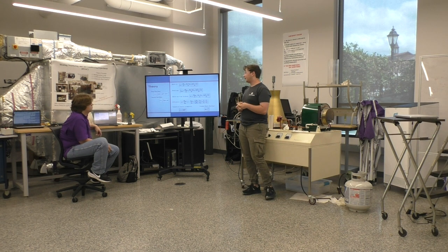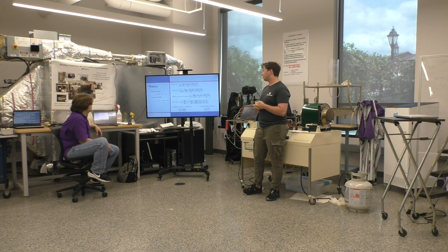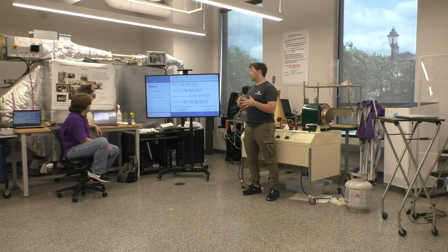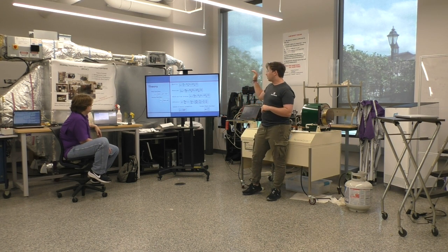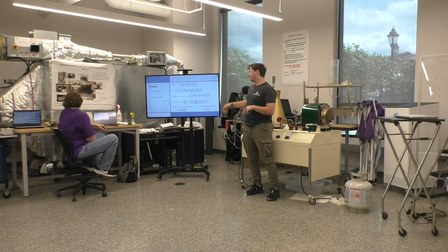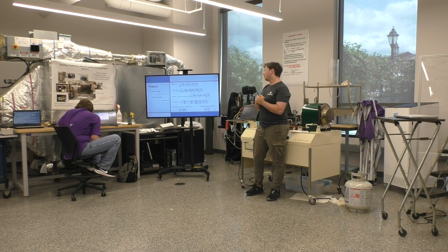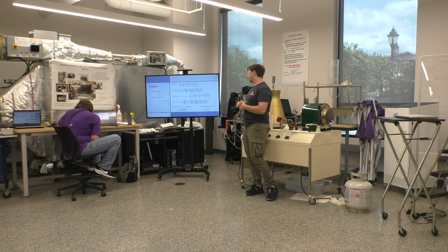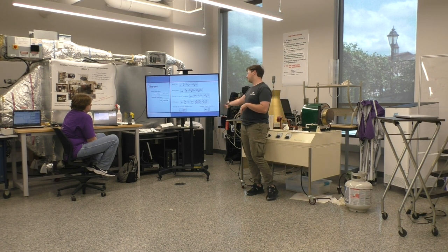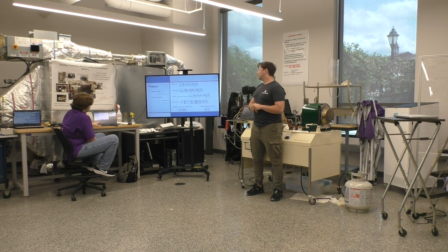So a little bit of the theory and the calculations that we'll be using. All the way on the right, there are the well-known ones, the mass flow rate, volume flow rate. We've all heard of those. In this specific experiment, we're going to be looking at the work put in and the work put out, and then the work done on the free turbine. And then we're going to take all those, get a net work, and calculate the efficiency and the intake Mach number down here, where it's velocity over the speed of sound in the medium, which is down right there.